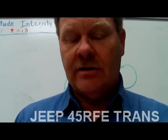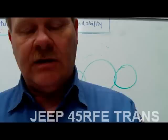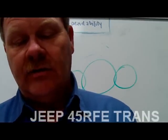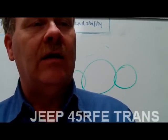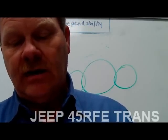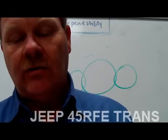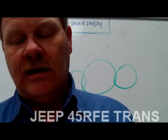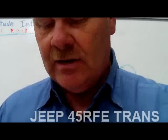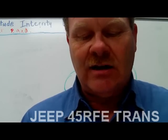You've got 3 planetary gear sets. I've already talked about that. Now we're getting over here to where we're going to answer our first question. It's fully electronically controlled. We need to familiarize ourselves with these. Well, they're not new now because this transmission's been out 10 years. The advantage of the electronic control is very consistent shift quality, with the driver feeling better shifts overall. Electronic control of things like shift points and line pressure can help improve durability and make a transmission last longer. Electronic control also facilitates the diagnosis of suspected transmission problems.